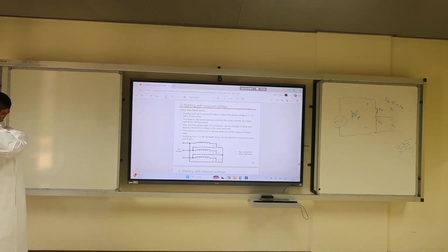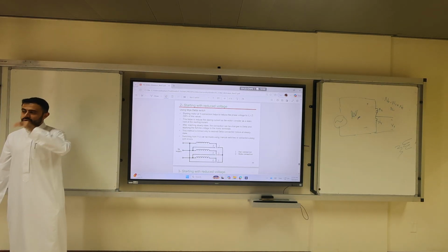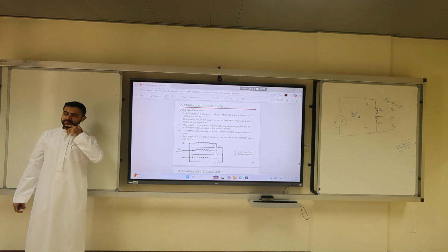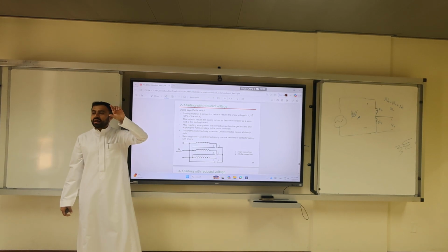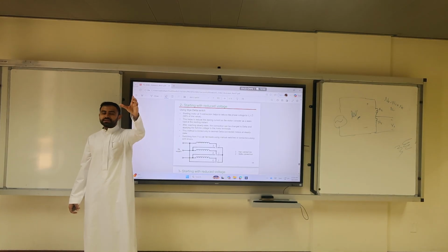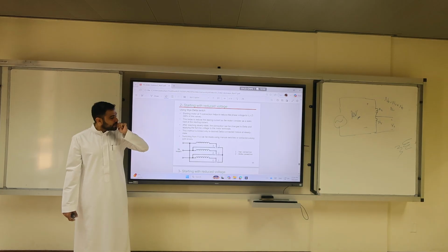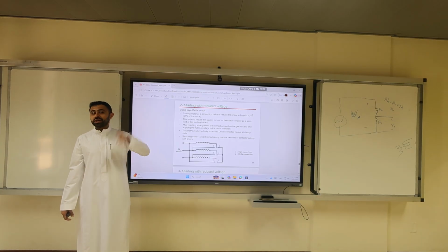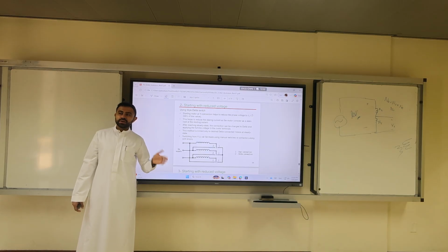We're talking about line voltage; what is the square root of 3? 1.7. So what is 1 over 1.7? 58%. What is 1 over square root of 3? 58. So you can reduce the supply voltage by 58% if you connect it in Y. So at the start, connect to Y. During operation, connect to delta.